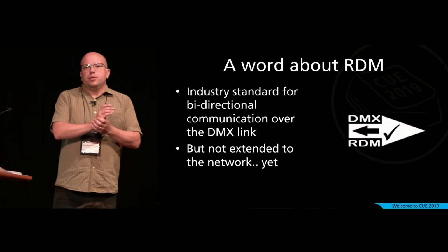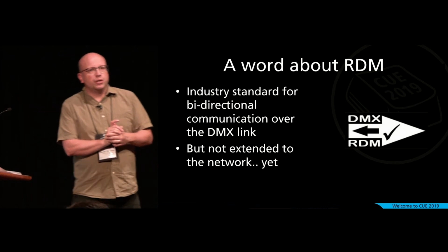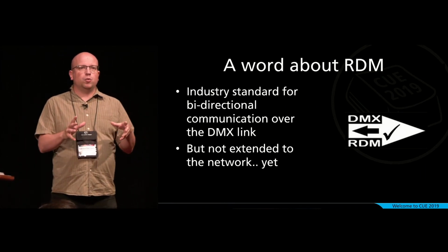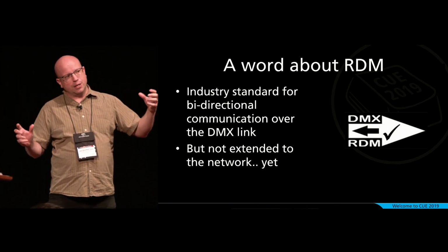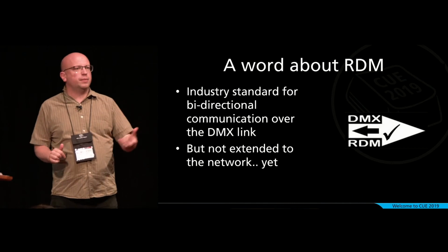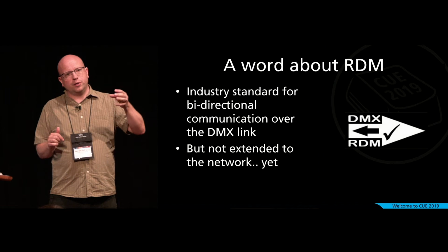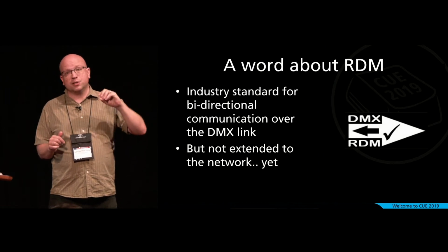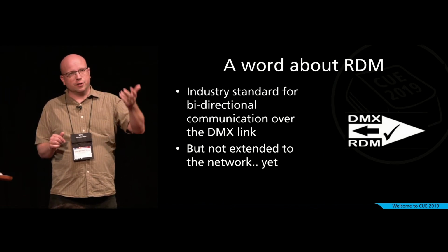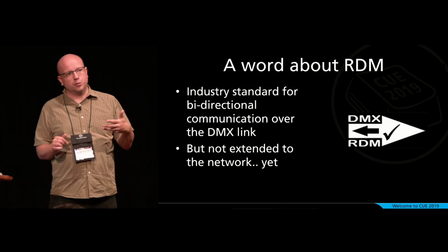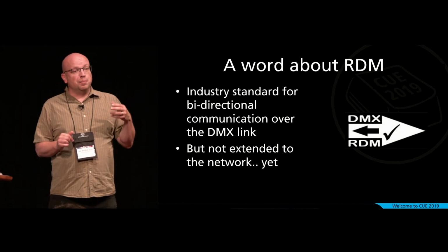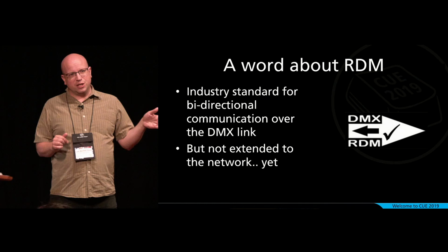So somebody asked earlier about RDM. So RDM has been pretty successful over the DMX wire, right? So you take your existing DMX wire and now you've got a tool like a DMX cat or Concert or whatever you like to use that can set up the lights at the far end of the wire. And that's great because it means now on my DMX wire, I can configure my lights, I can set my DMX addresses without getting out the ladder, but it ends at the end of the DMX wire.